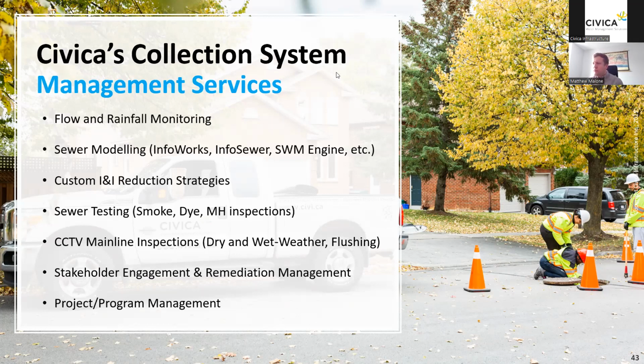So I think most of our rain gauges, especially if we're hooking up to a heater element, we don't want the heater on all the time. So they do measure temperature so that if it gets below a certain temperature, the heater can kick on. So that is one way to monitor temperature. I mean, there are pretty cost-effective temperature probes, temperature monitors, that we can put out with rain gauges, for example, and connect to the same loggers.